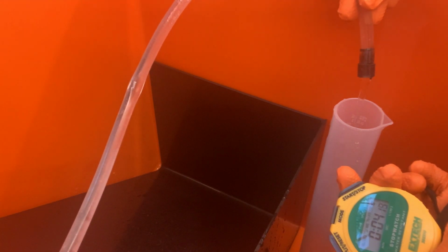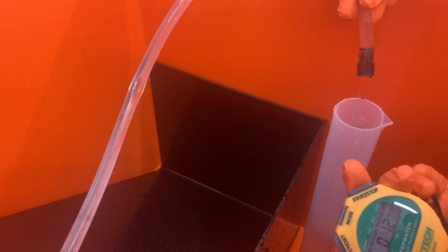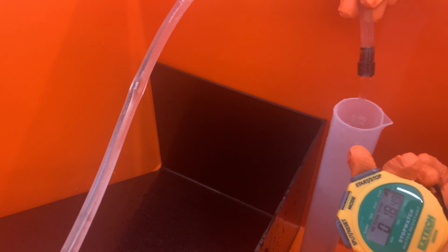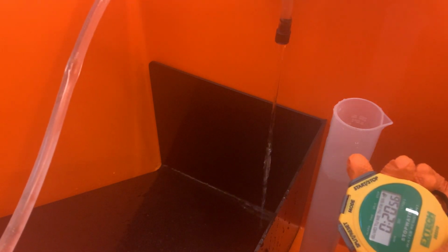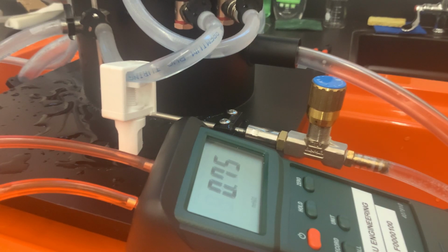So what I'm doing is collecting water. Instead of collecting water in the tank, I'm collecting in the beaker, so it takes less time. I'm collecting the water for about 15 or 20 seconds. So let's stop. So this is the water collected in 20 seconds. So I can take the reading now. The reading is about 215 milliliters. So this is all we have to do repeatedly for the major head loss, friction loss at high flow rate.